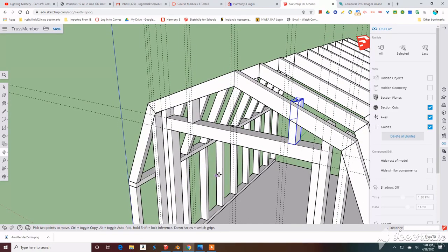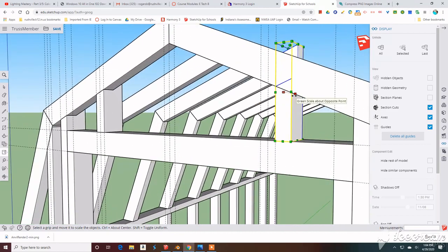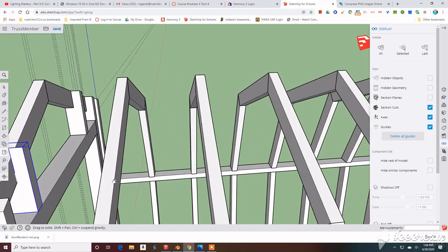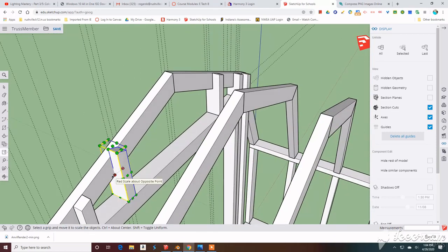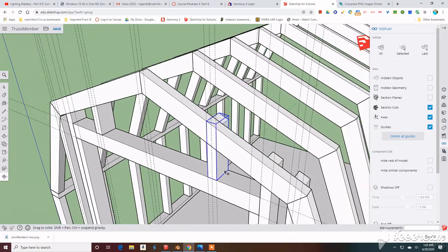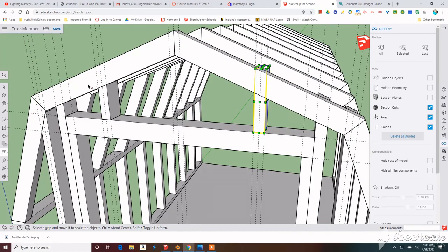I'm going to use my scale tool there by pressing the S button. And now I am just going to flip that around. Okay. So I can barely see that middle handle there, and that's the one we want to click on. And so all I'm going to do here is just click and drag this over until, in the distance, it says -1. That means it's flipped itself around the line of symmetry there. And so now it's in the correct spot.